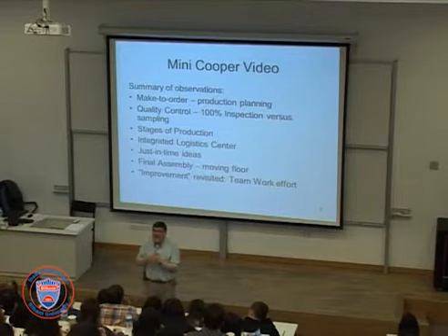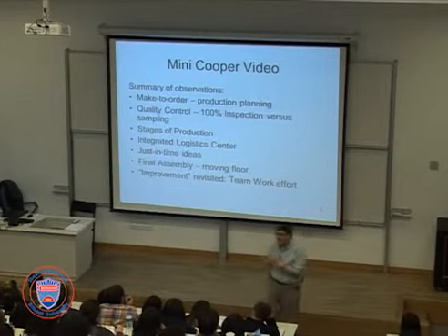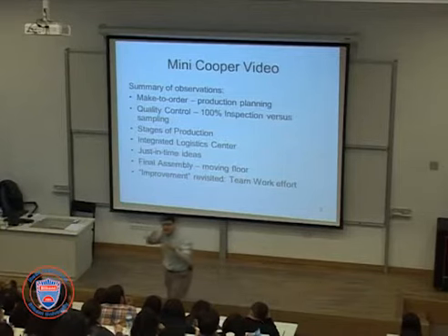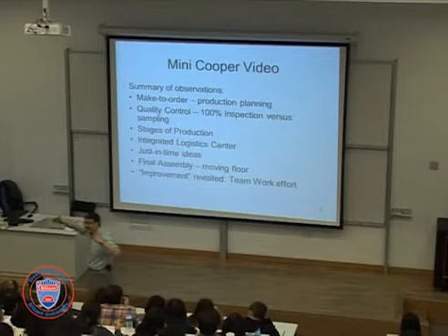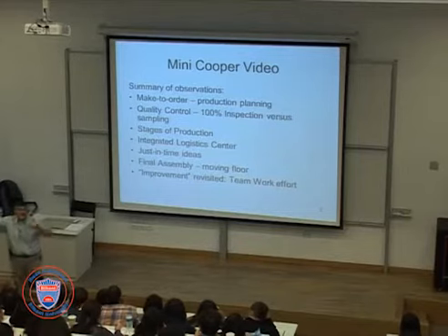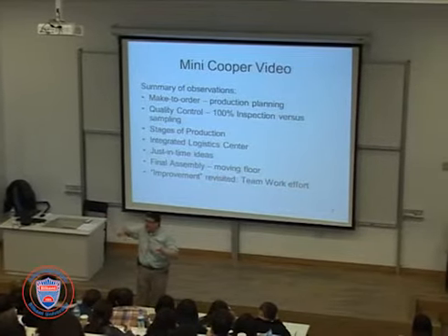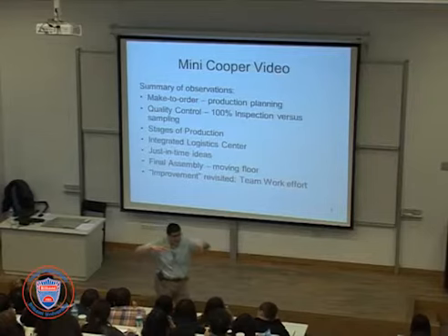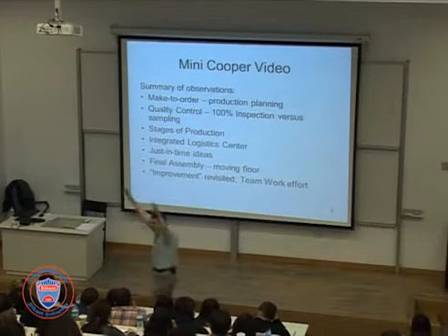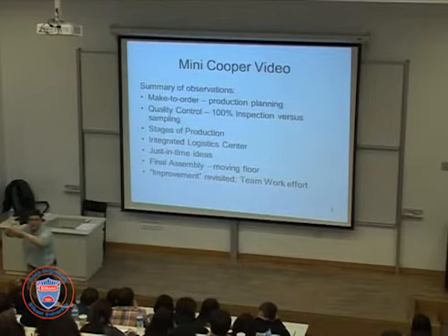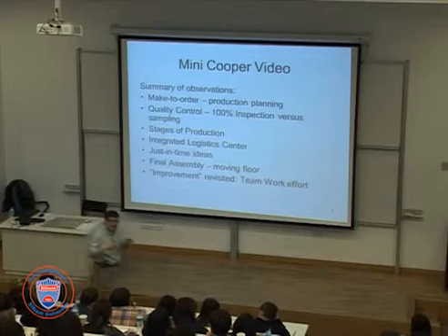I can tell you that in 1920s, when the first assembly line was established, painting was also a part of the assembly line. But throughout the years, because of the toxicity that is created by painting operation, and at the same time the length of that operation, it was required that it should take place in another location. Moreover, the process which is used actually takes a number of them together and puts them for drying. So you don't dry it one by one, but you put it in a large oven so that they will be dried all together. So the batching of the items is also another reason why it is not part of it.